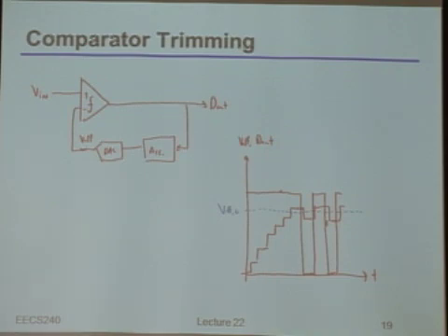Okay, great. There's actually a couple of other ways you can interpret this. As you're running this thing, what you're really doing is adjusting the threshold of that comparator. So let me just quickly draw that, because sometimes it does help people to understand the general concept. Remember with a comparator, what we're basically looking at is a V out versus V in curve that, as an example, let's say I had an initial offset, would look something like this.